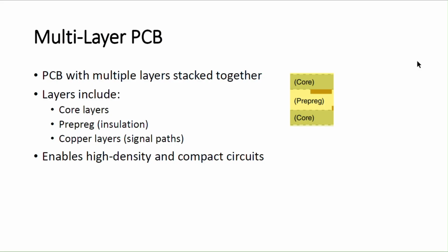So sometimes, for example, the board thickness may vary from 0.8 mm to 1.6 or 2.65. Sometimes you may need to prepare a 3.2 mm printed circuit board. This is based on different types of application and the number of layers of the printed circuit board, like how many layers you want to stack up, whether you need a 4 layer PCB, 6 layer PCB, 8 layer PCB, like that. All these factors will give you control over the layer arrangement.